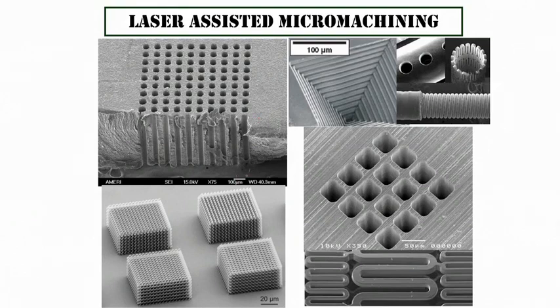If this length scale is 100 micrometer here, then we are talking about features that are several hundred micrometers deep, maybe almost half a millimeter depth of cut, with sharp and completely smooth vertical walls of cut. The diameter of these holes could easily be some 20-30 micrometer, so extremely fine size.